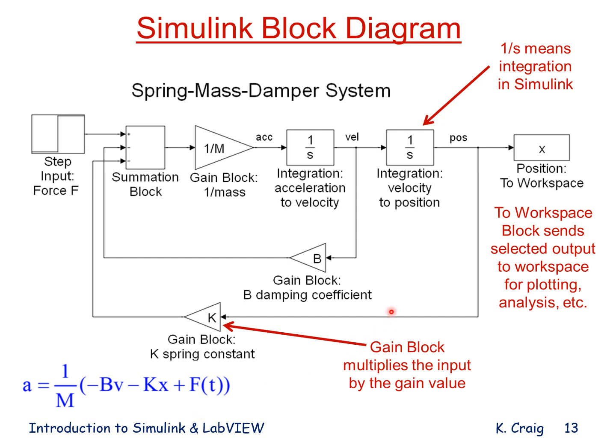How do I know my block diagram is correct? Well, there is never any reason why your block diagram should be different from your equation of motion or equations of motion. The reason is because the last step in the whole process is to write the equation of motion from the block diagram. Now, the equation may be incorrect, but the block diagram should always be consistent with the equation. There's no reason for it not to be if you perform this step. So let me perform this step.